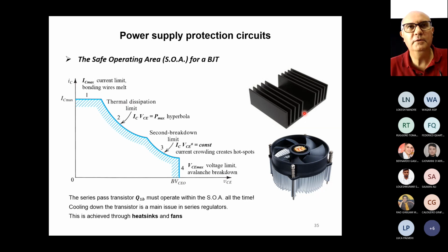That's a big problem because you must take off the heat from the hot spots and bring it out. So usually you have a large heat sink. It's like in the car where you have the radiator. It works in the same way. Otherwise, the chip will die.